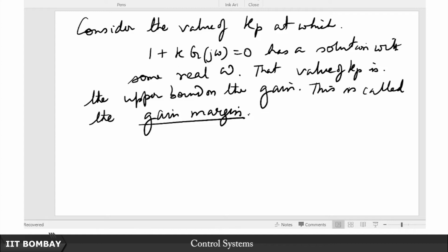Of course, you might say there are some pathological cases like we have already discussed some here. So, for example, sometimes we have some sort of a pole zero configuration like this, where you have one crossover here and another crossover here, and one crossover here and another crossover here. We have seen something like this in root locus, right. I believe this was what that particular root locus looked like, if I am not mistaken, right.